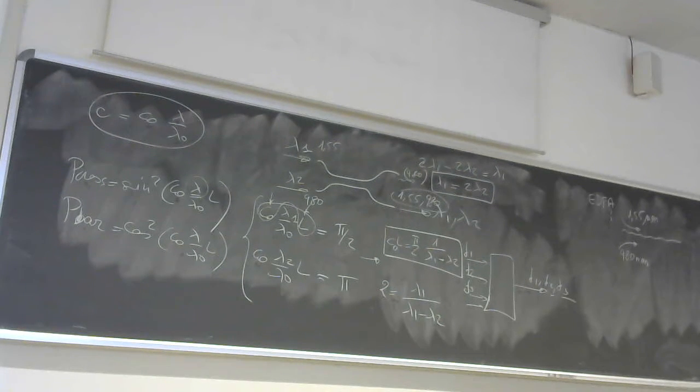C0 because this depends on the shape of the waveguide, on the technology, on the refractive index, the distance of the waveguide, a lot of technological constraints. So C0, you can choose, but you cannot choose very much because it comes from everything else, from the waveguide. You can only choose one. Yes, basically. You can change C a little bit by changing the distance between the two waveguides.